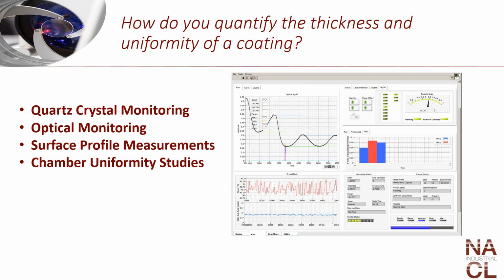So as the oscillation tells our PLC we've reached the desired thickness of material A, we have a rotational carousel at the bottom with different evaporative materials. So evaporative material A reaches the appropriate thickness, the carousel turns, evaporative material B is then evaporated, goes airborne, and starts bombarding the quartz crystal. So it's really all of that frequency oscillation with the quartz crystal monitored at the same height as the substrates that tell us how thick our coating is, layer by layer.